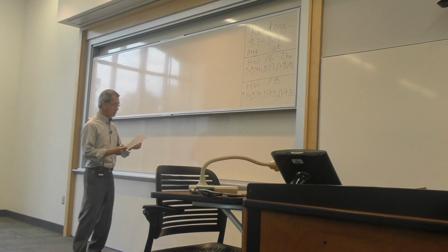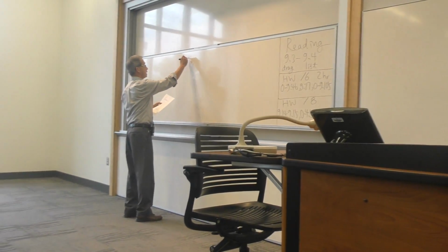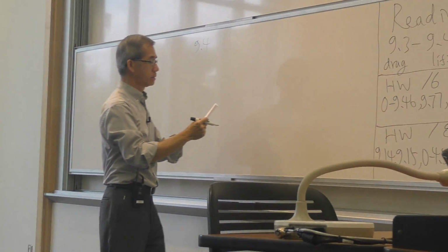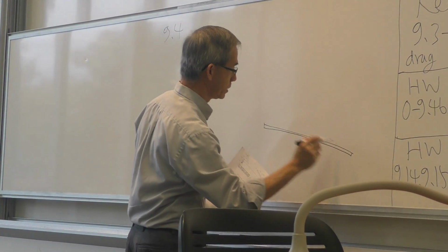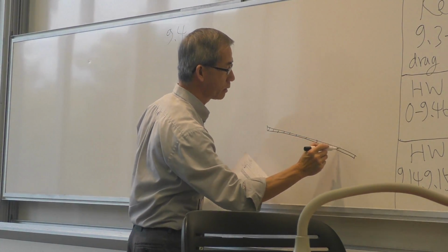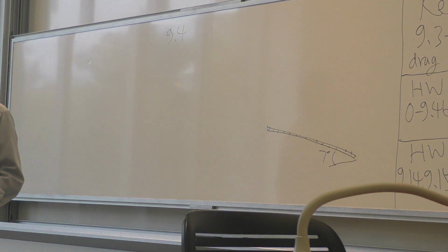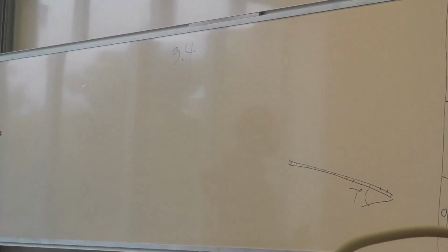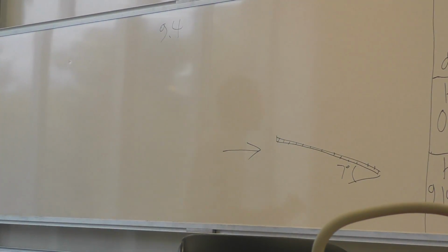Okay, I just want to touch on the problem where the plate is oriented at an angle, and this is a little bit detailed. I think the problem of resolving the drag and the lift is actually quite straightforward, nothing but geometry. What I want to use this to illustrate is the direction of the forces between the shear acting on the fluid versus the shear acting on the plate. It's a little subtle, but once and for all, it's important to see the distinction.